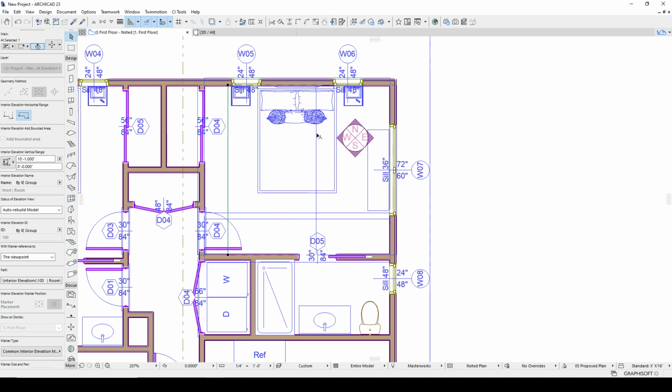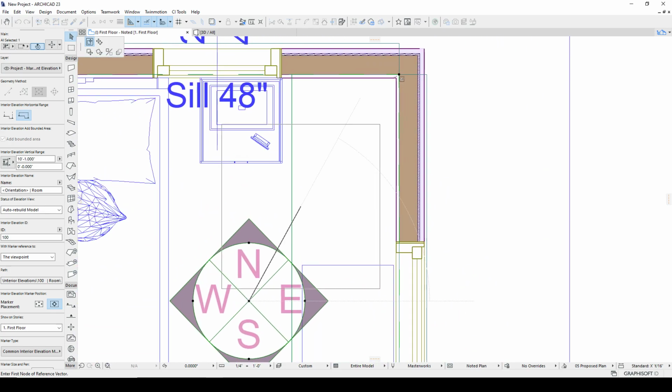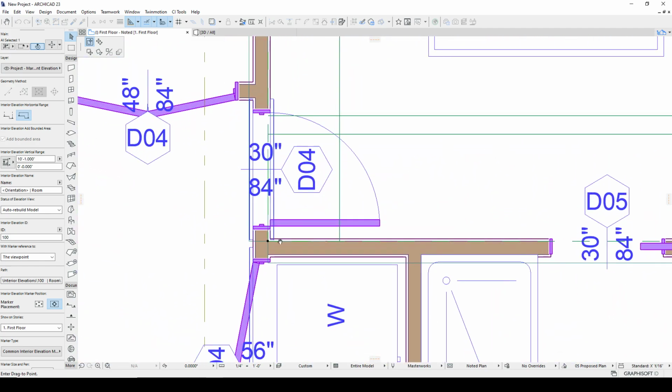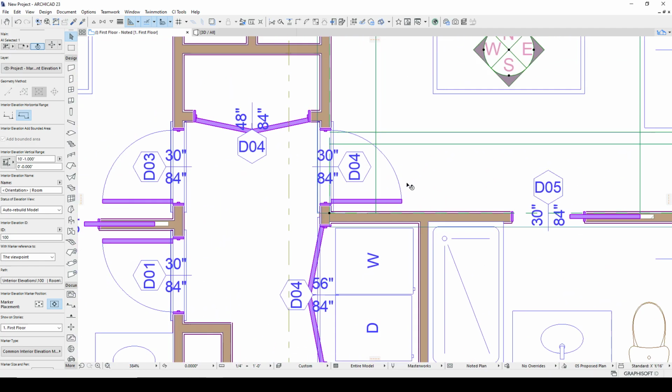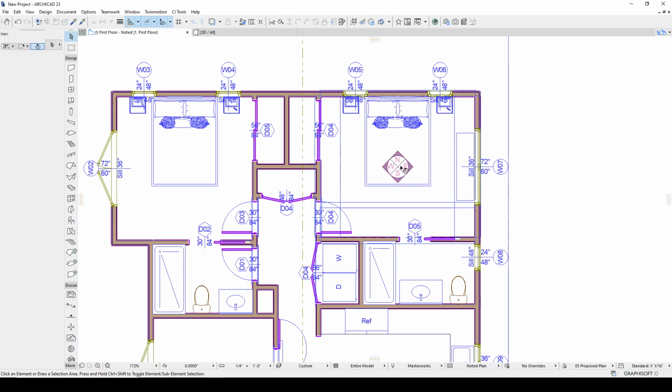You can also do jogs in these markers. There's a couple of features here so you can break the offset. If you need to jog around some obstacles, we can bring this into the center. I'll use the semicolon. So I start moving it, hit the semicolon, and then just click the two corners of the room, and that'll select the center between those two clicks.